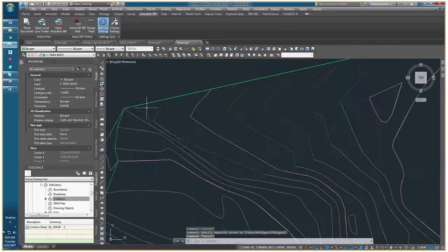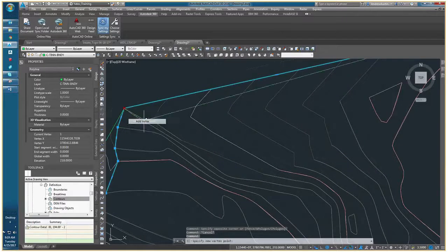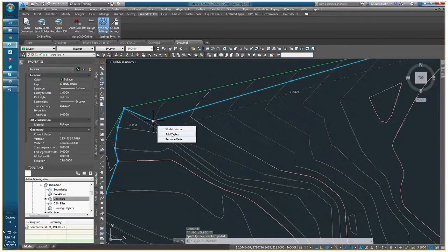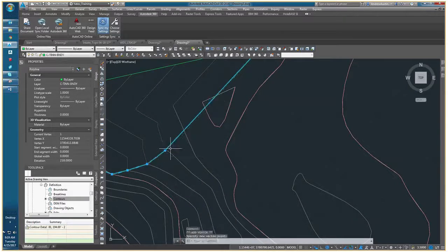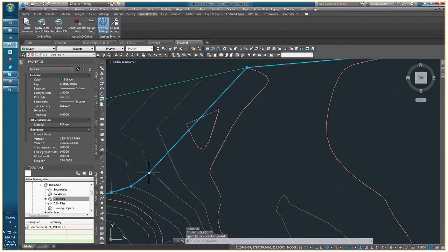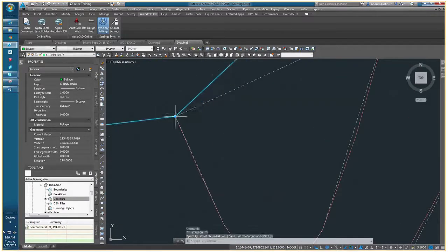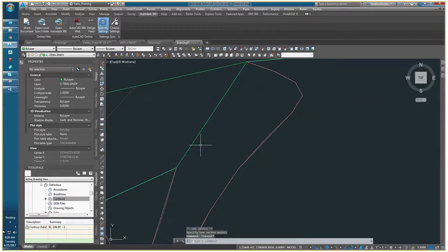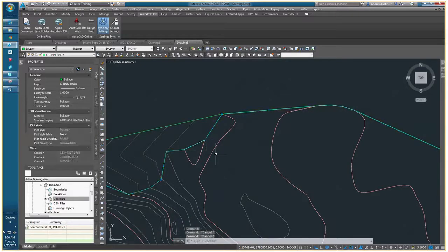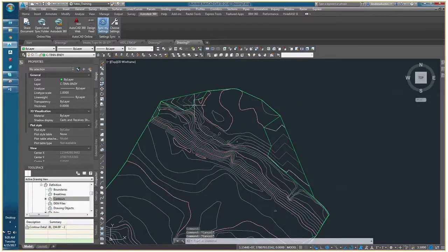All right. We're not done yet. You see there I clicked on, I snapped to inadvertently a separate endpoint. So just be very careful when you're using those snaps that you snap to the intended target. All right, now we have a better defined boundary.